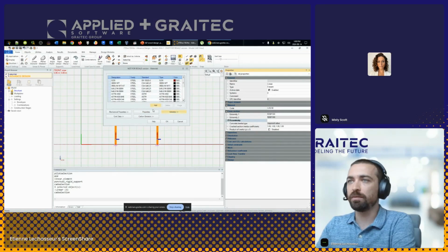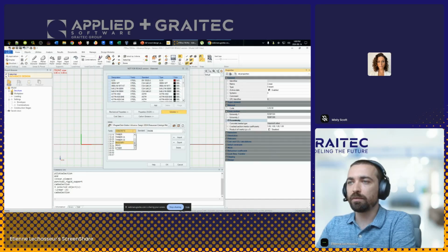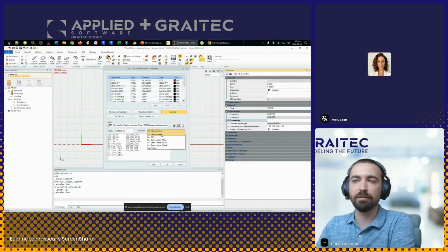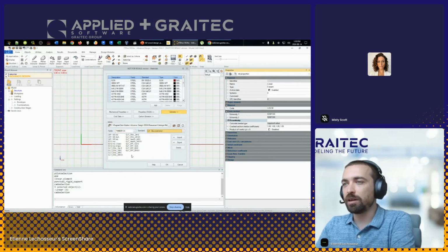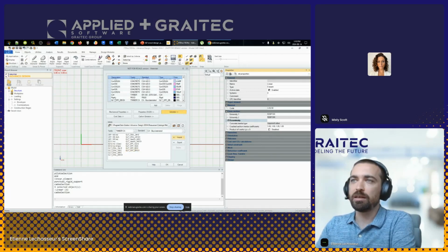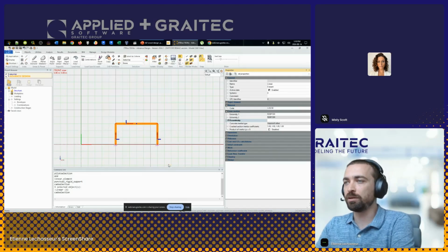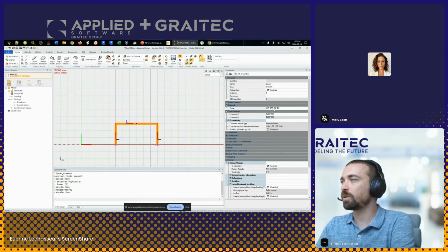They're sorted by category, so I'll start here with timber CA and select the glue-laminated category. If I want to, for example, use the SPF 20FEX, I will import it, and now it will be in the quick access list. If I select it, when I close the dialog box, it will automatically apply it to the members. As you can see, I have the GLT material.